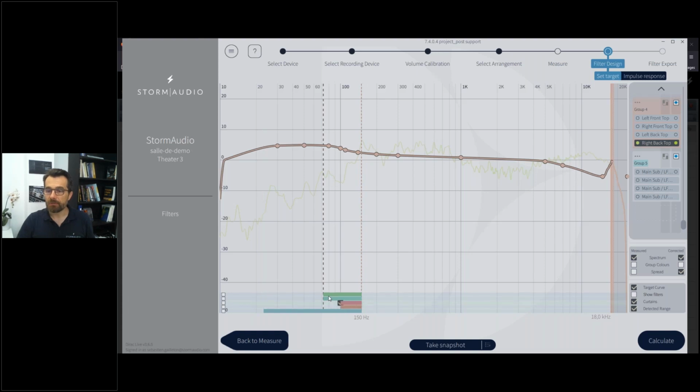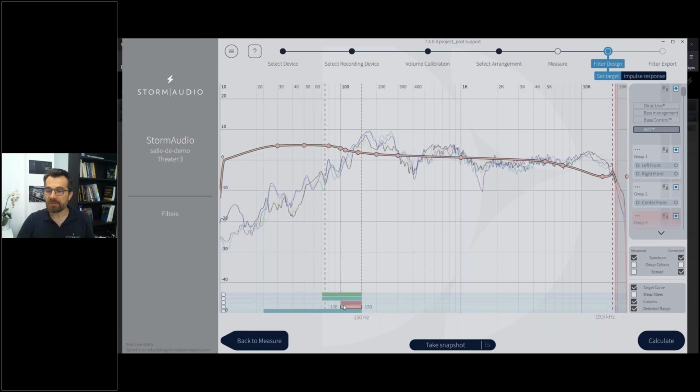Whenever you're done with the support range definition, as I mentioned, you have made sure that here the frequencies are correctly adjusted. So I limited to 100 Hz my different S150 speakers. I limited to 70 Hz low frequency my 300 LCR speakers. Now I'm happy. The next step is to load the target curve.